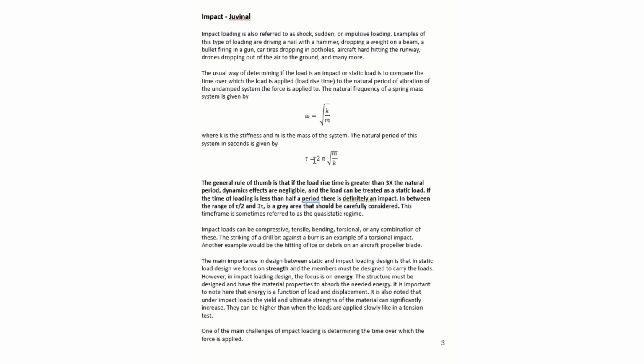And the general rule of thumb is that if the load rise, so we apply the load, and if that load rise from initial application to maximum load is greater than 3 times the natural period, then the dynamic effects are negligible and the load can be treated as a simple static load.